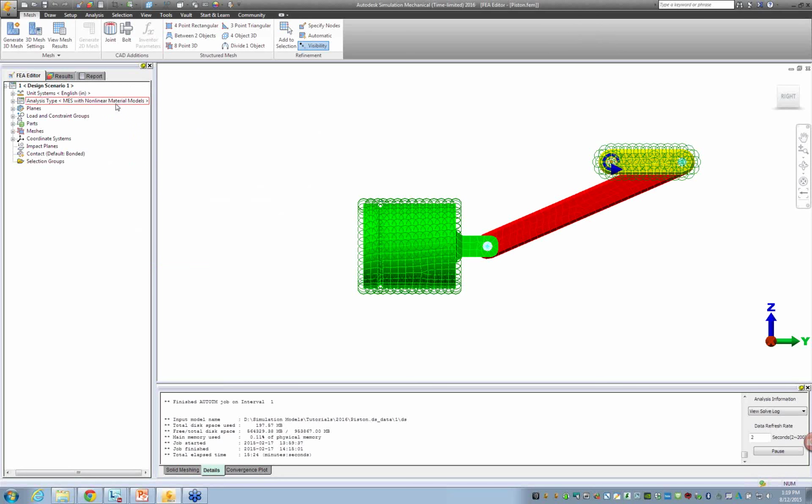Another alternative that you have whenever you're trying to analyze systems like this and are interested in looking at the stress and deformation results within single parts in an assembly while the assembly is in motion, is doing an interoperability workflow with a multi-body dynamics simulation tool, such as Recurdyn. So to do that, you would have to do the following.